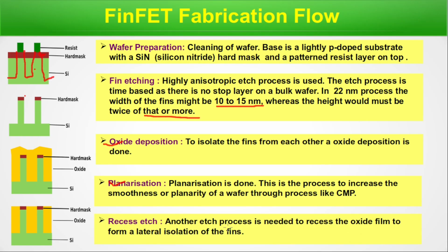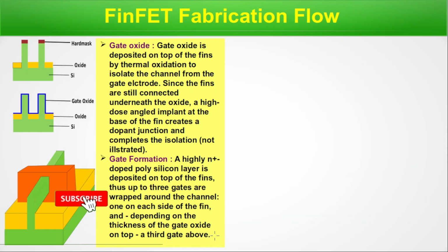Another etch process is needed to recess the oxide film to form a lateral isolation of the fins. We will recess from here. We will remove oxide. Keeping some, we will remove some oxide. We will see that step in next slide. These are the next steps.